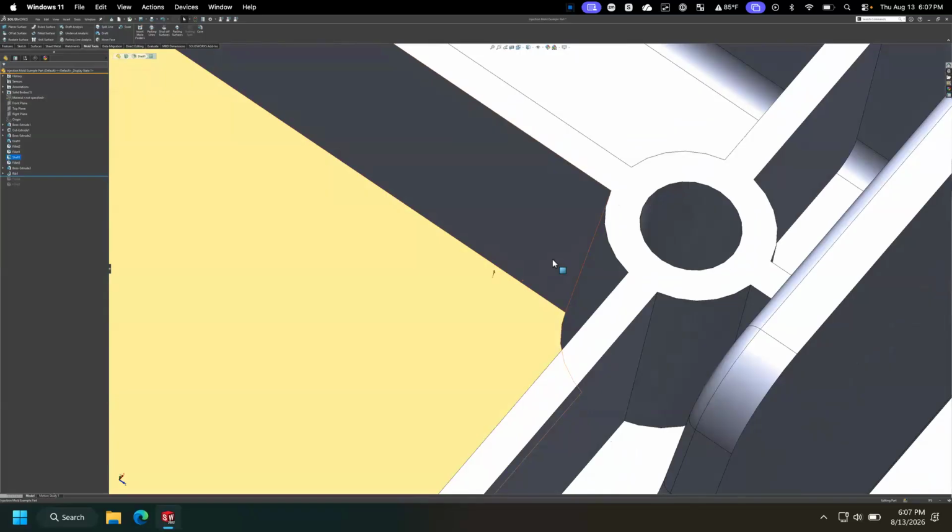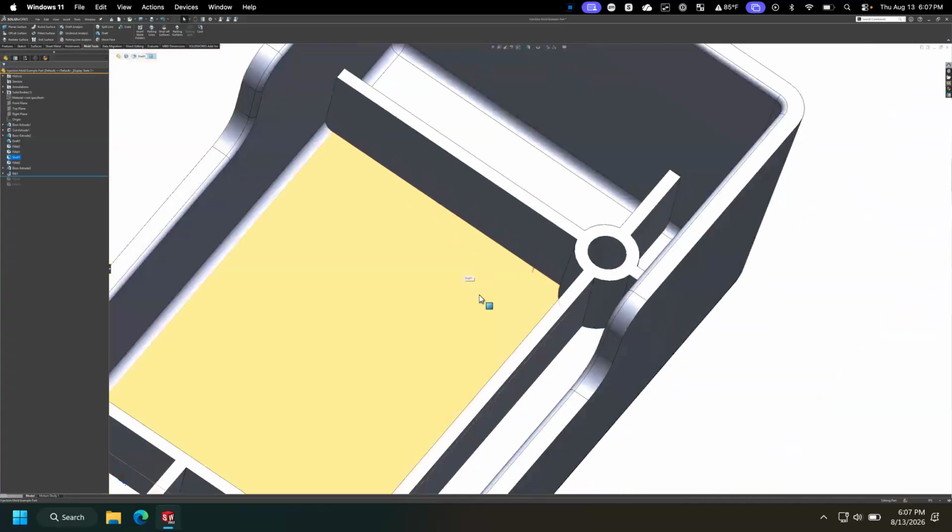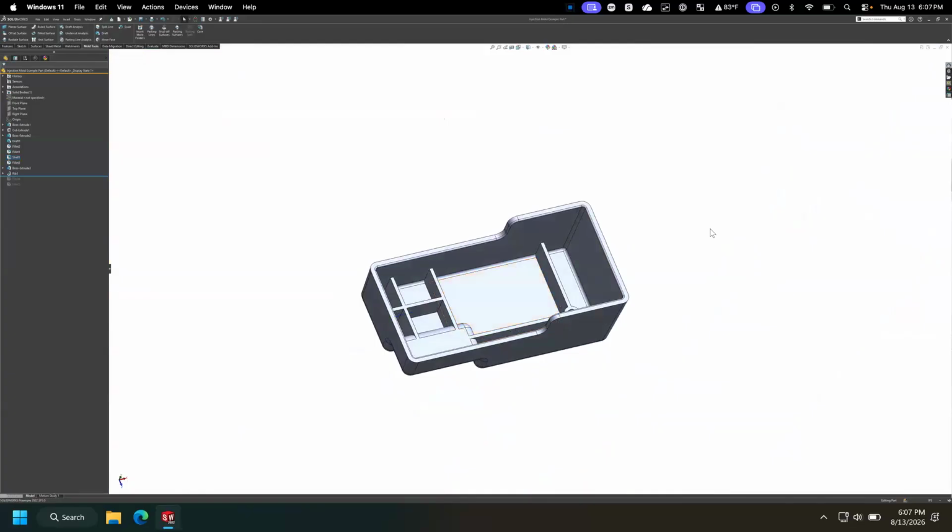But there are a couple things you may consider, and I don't know if the mold flow touches on this, but also life of tool. If you've got hard edges, inevitably your edge on your mold will wear. So you may want to plan a radius. The other thing to consider, which is kind of an interesting thing, is that when you're designing for injection molding, you have to think of it backwards, also in terms of designing for manufacturing of the CNC in the mold.